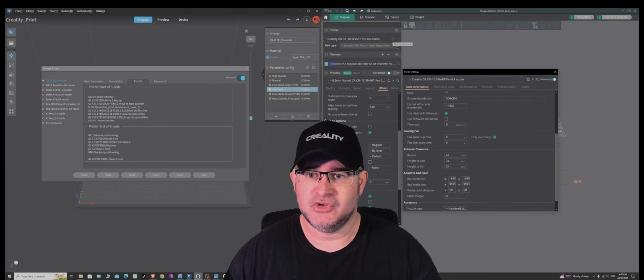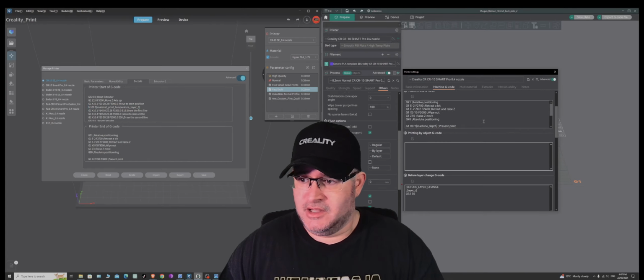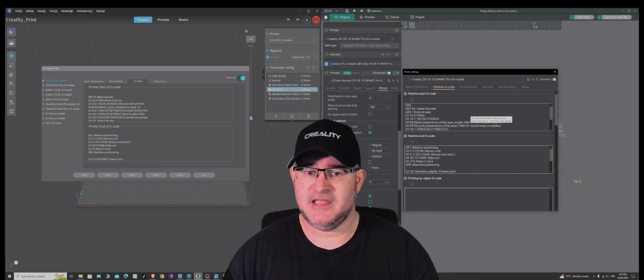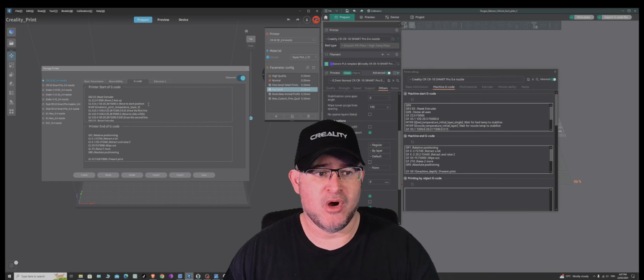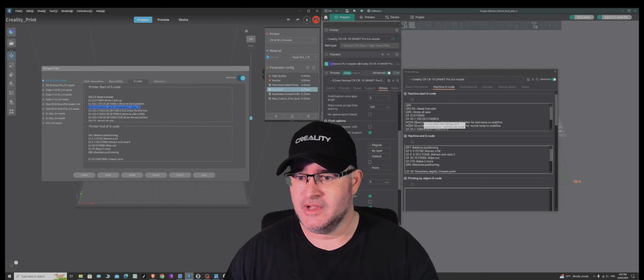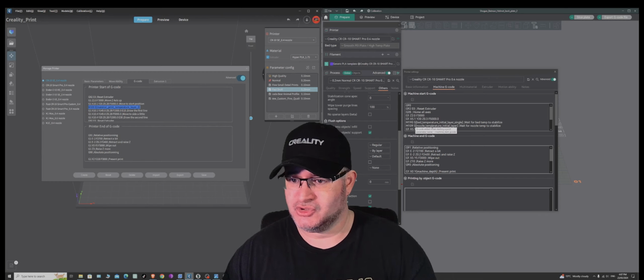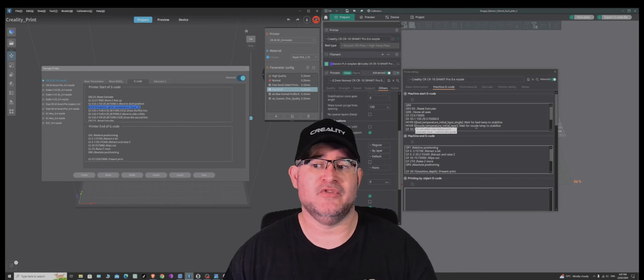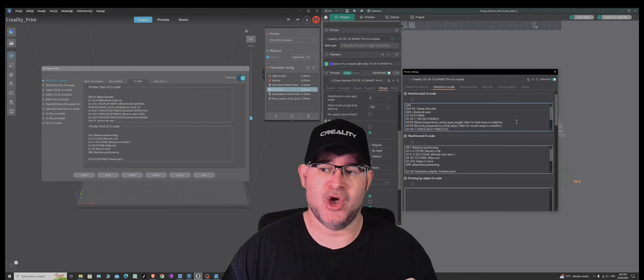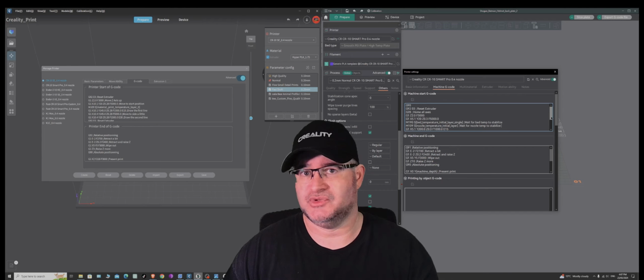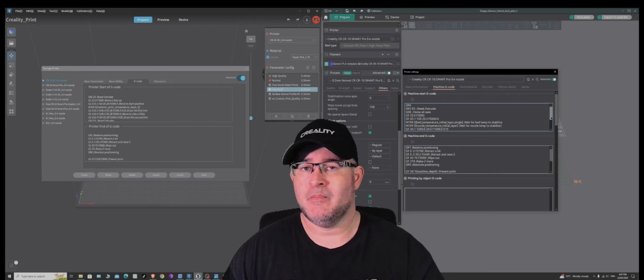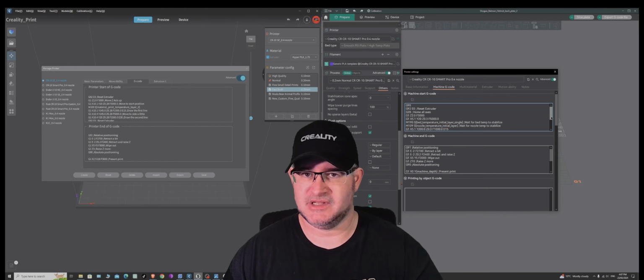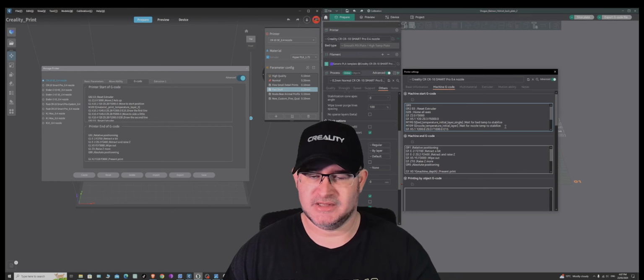When we go into the G-code here, you'll see at the very top, the difference is, once again, M109 material print temperature layer 0, and as it says in Orca, it says nozzle temperature initial layer, wait for nozzle temperature to stabilize. So basically what it's saying is Orca's wanting to know that the actual nozzle temperature has not only heated up, but has actually stabilized to the right temperature, because sometimes you can go above, and that's to make sure that when it starts the print, it's at the exact correct temperature. So that's another requirement that Orca requires.